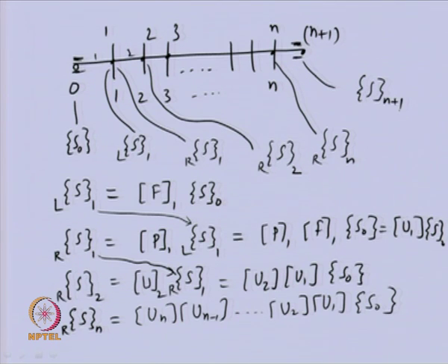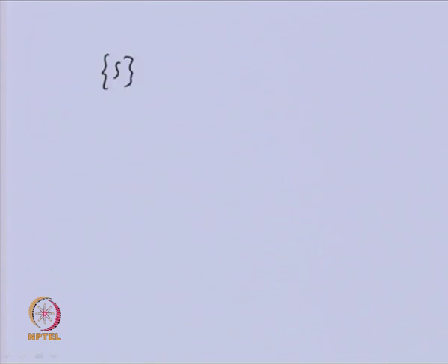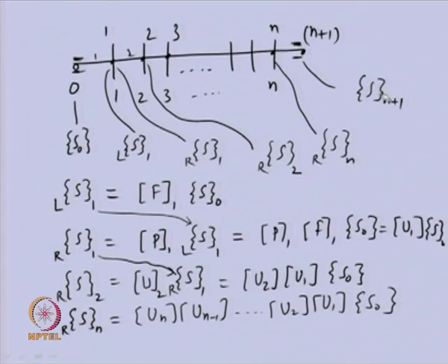So, this we can do in the next slide. State vector n plus 1, because there is no disk here, so we are not attaching any left and right, is related with the state vector on the right of disk 2 with a field matrix, that is n plus 1. So, you can see, go back. This particular state vector and this are related by a field matrix, this particular shaft which is n plus 1th shaft. So, we need to pre-multiply this with the field matrix of this shaft to get the